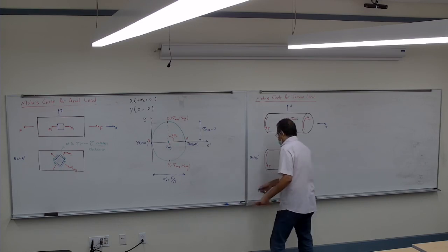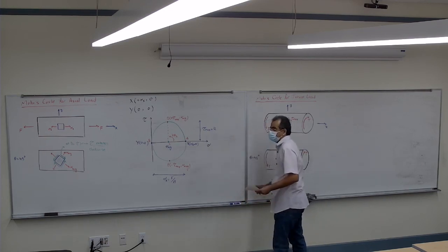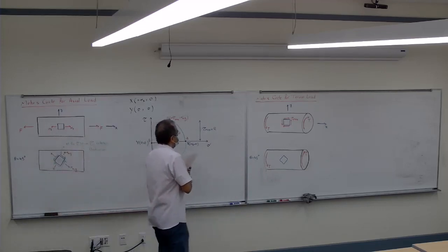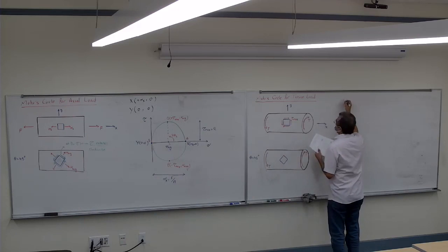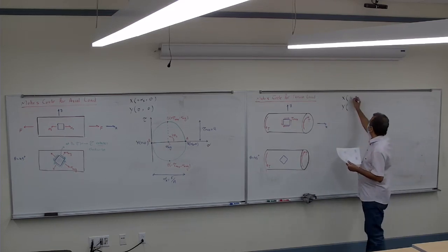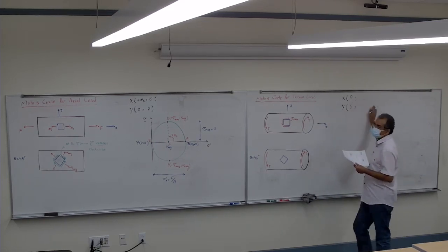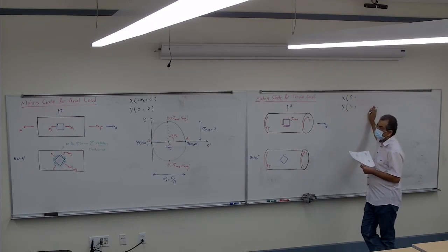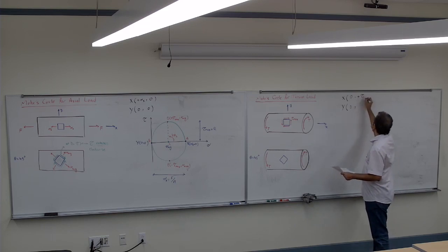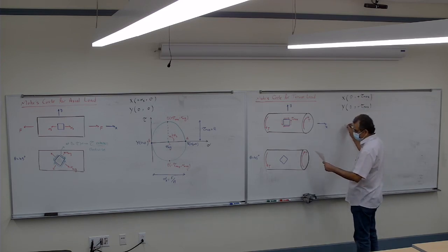Before I do that, I will go ahead and draw a Mohr circle for this one. I'm going to draw the x and y. So what's the x and y? 0, 0. And the top is tau max, and negative tau max. This guy was tau max and negative tau max. So if I go ahead and draw the Mohr circle,